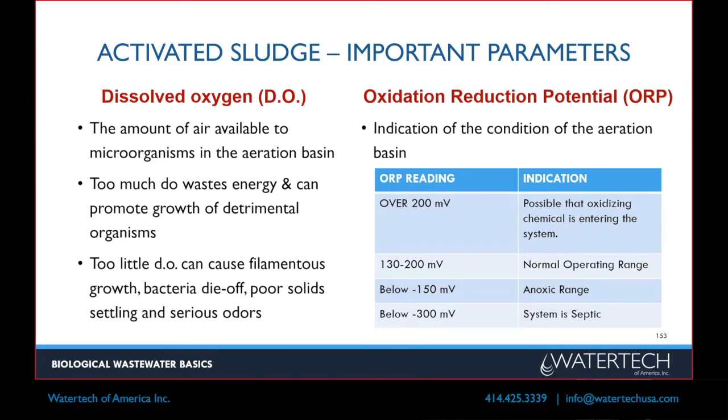If you go too long with not enough air, you start to go septic, and that means your whole system stinks. I worked at Golden Guernsey Dairy, they're not in business anymore, but they had a wastewater plant out in Waukesha. It was the first time I was in wastewater, right across from the county fairgrounds. We had a system go septic on us right across the street during the fair, and there were all sorts of complaints about odors blowing over onto the fairgoers.